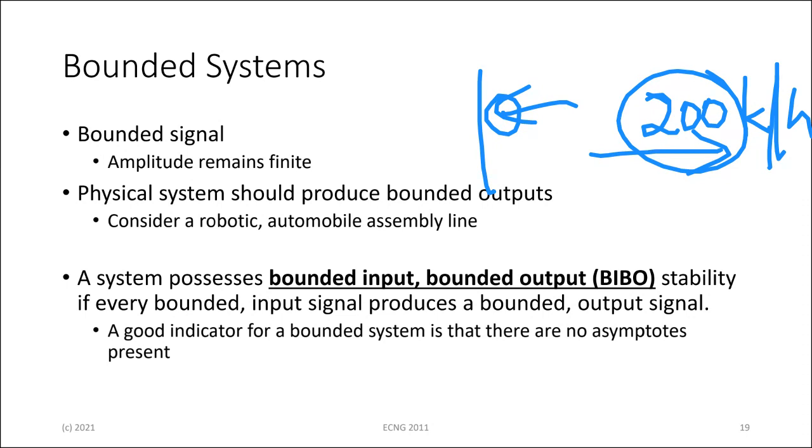All right, so there are boilers that operate at, say, 3,000 psi, pounds per square inch. So what happens if the fuel line sticks, and the boiler is heating up continually, or it's an electric unit, and the thermostat fails and it keeps getting current, and it keeps increasing the pressure beyond 3,000? What's going to happen? It's going to fail, and people are going to get hurt. So that's why it's absolutely imperative that when you're dealing with systems, you have bounded systems.